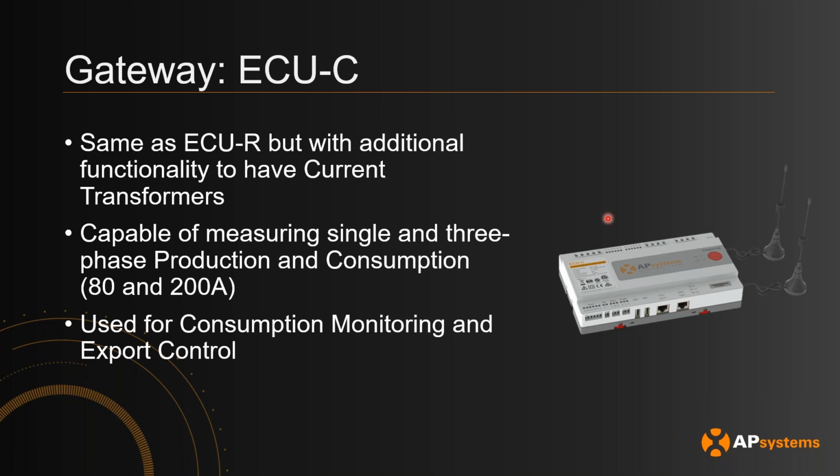where you can put current transformers onto them, and that allows you to do consumption monitoring, CT measurements, and export control. It's not necessary for every project, but if you notice that there's a requirement where you need to have that sort of monitoring information, that's the way to go.